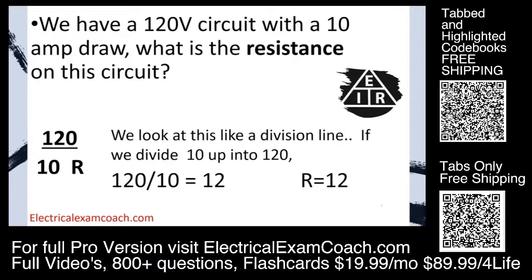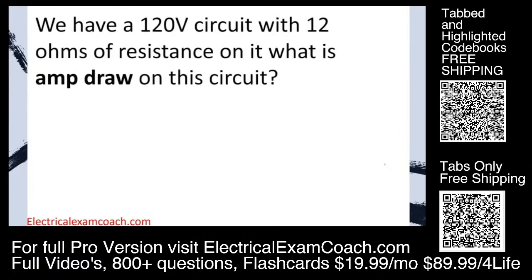If I don't have that, there's something wrong. There's something failed, there's something broken, there's something disconnected, there's something causing more resistance that's gotten in the circuit. It's really great for troubleshooting. And I know that it's going to unlock a lot for you, not only with your testing, but also out in the field. In this case, we have a 120 volt circuit with 12 ohms of resistance on it.